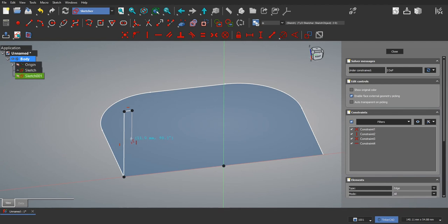I want another vertical line, a small horizontal line again, and then I want this to go down vertically, and I want it to be on that axis, and then one more here to close it all out. And we try to move stuff around just to make sure it is in fact constrained. I can't move this one, so that one's in place. This one can be moved.